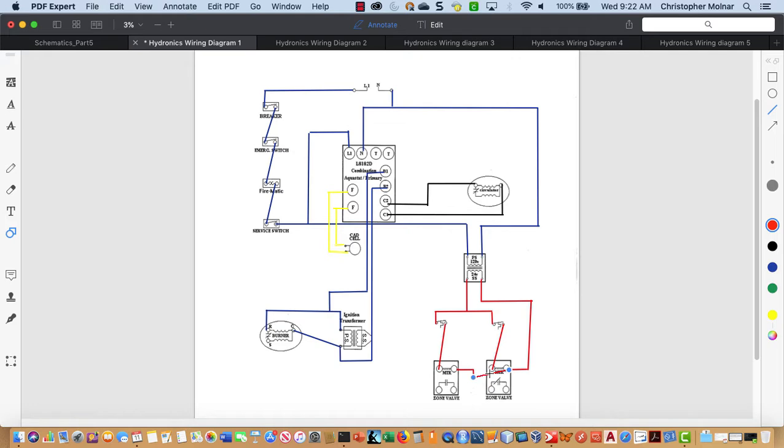And you can junction one off the other, as long as you're on the right side. So we're going to go ahead and do that. Now our zone valves will open. We have two final terminals. Our zone valves have an end switch. End switches are always wired in parallel so that if either zone valve is open, we make the terminal connection to T and T.